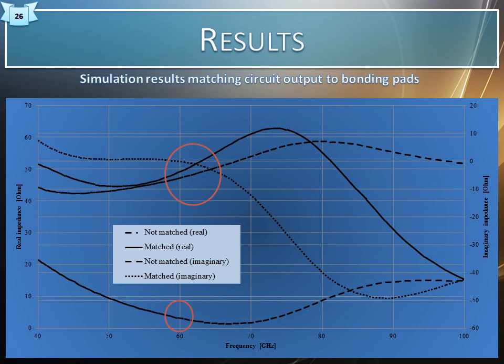The matching circuit operates as required and designed, where it can be noted from the results in this figure that the real and imaginary impedance of the output at 60 GHz are in fact 50 and 0 ohm respectively. The buffer circuit also assists, without changing the transfer characteristics at the frequency of importance, so that no external loading occurs when measurements are conducted.